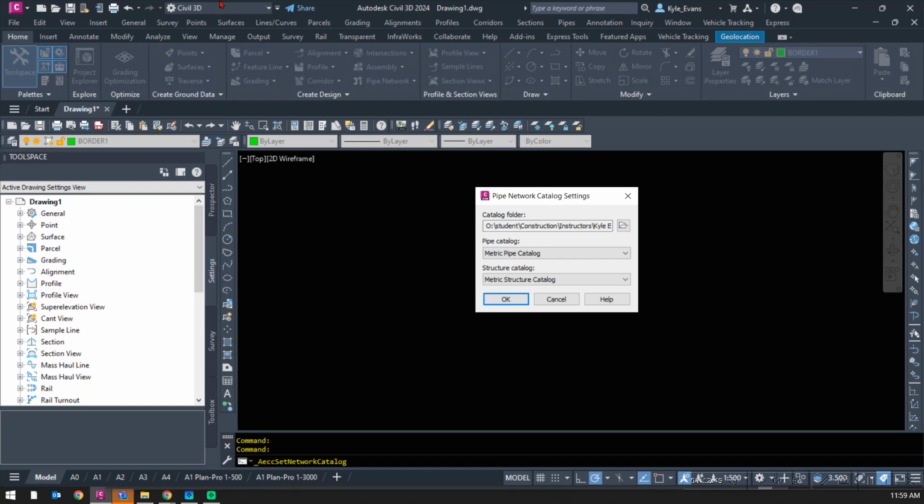It should be linked to the folder we're going to set up tomorrow. Right now, mine is set up for the O drive. So I'm going to come in here and double confirm it's referencing the same location, because if I start drawing pipes and I don't check this and it's somewhere else, I'm going to break my pipes. I'm going to have to start again. You guys don't have time for that. So just double check. It takes 15 seconds.